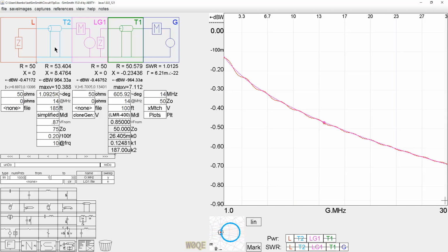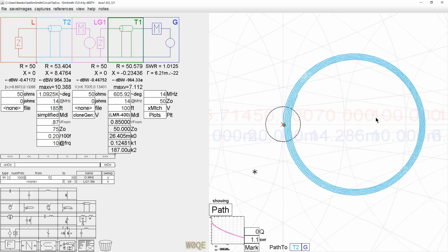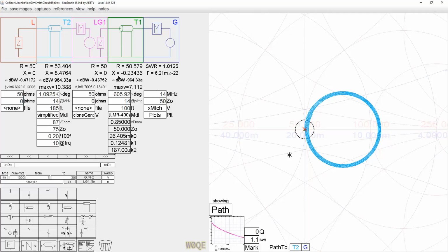So when we do this, we'll see a couple of things, because it's still not exactly apples to apples. Let's look at the Smith chart for a moment. What we see is that the 75 ohm cable TV free coax rotates around this circle here with a 50 ohm load. It's got a 1.5 to 1 SWR. It rotates between 50 ohms and somewhere out here 110, 120 ohms.